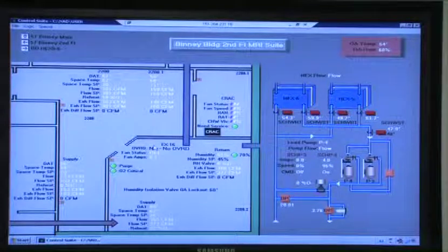Right, so the exhaust damper opens and the exhaust fan starts. There's a damper on the return, like a Belimo on the return, and there's a Belimo on the exhaust. When it goes into purge mode, it closes the return. That normally open damper closes, and then the normally closed damper on the exhaust opens up to exhaust it out through the exhaust fan. The supply stays the same.